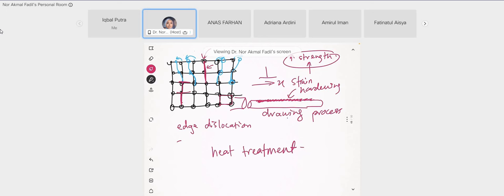After the drawing process, the original microstructure becomes elongated, and this microstructure also promotes the high strength properties. So maybe we want the microstructure changes to dominate the strength properties, not the multiple residual stress or strain that increases the density inside the microstructure.